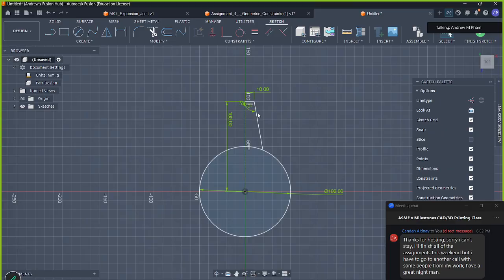So you see here, we have this half tooth with this construction line. You'll notice that only this area is highlighted blue, because this is closed geometry. The circle fully encloses itself. And here, we have this construction line. It does visually close it off.